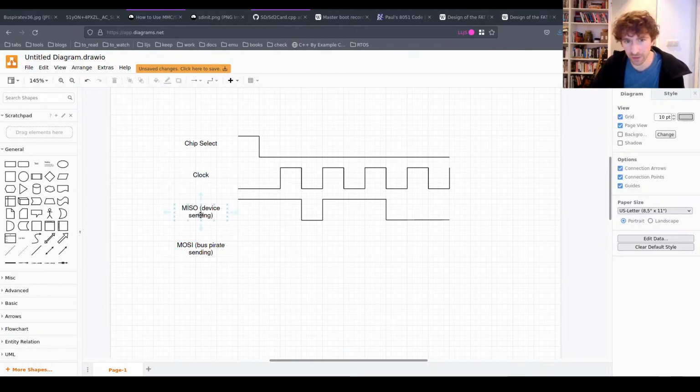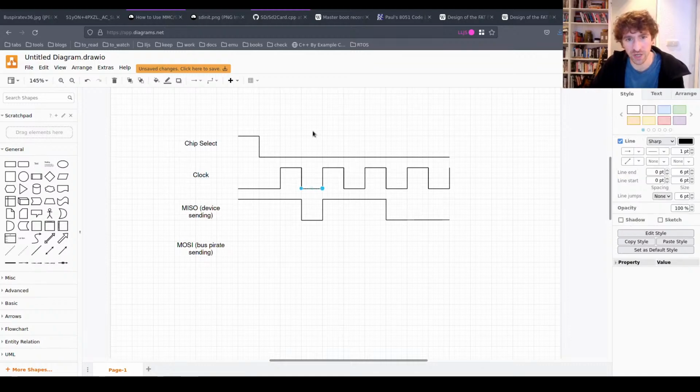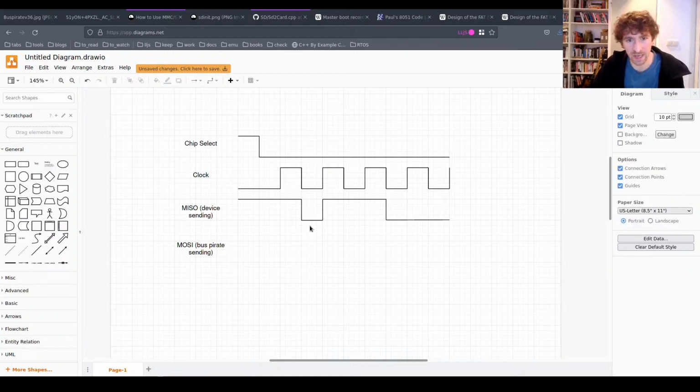Okay, so the main device, let's look at how this would be. When the clock goes from high to low is when we are checking the data. So here, at this point, clock goes from high to low, we check in the middle of the frame, and this would be a 0. Then again, we go from high to low, we check again, this one would be a 1.